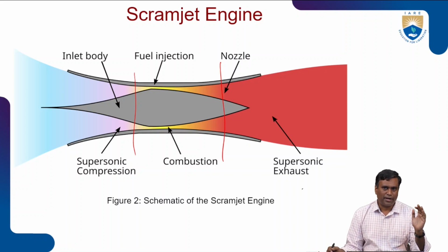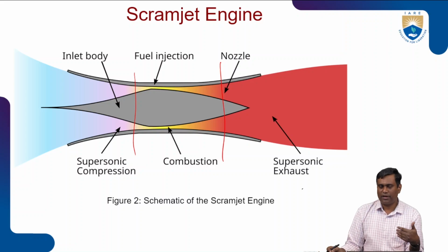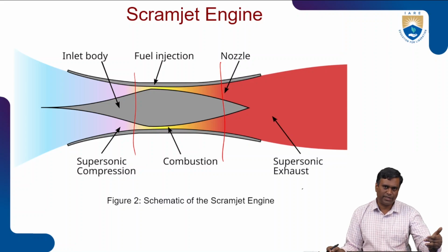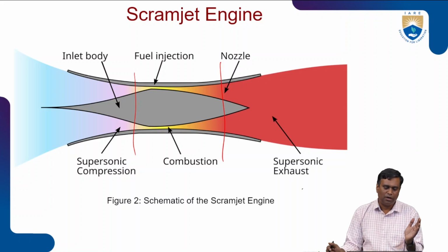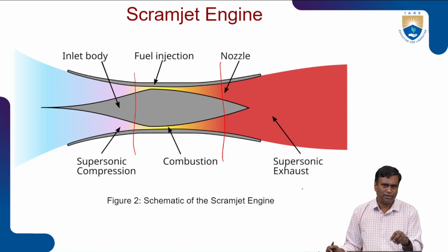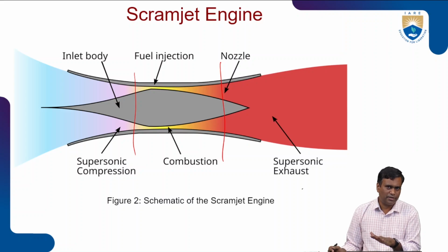In the ramjet case, that particular inlet should handle that and decelerate, right? In both cases, with the help of oblique shock waves and a normal shock wave, the deceleration takes place, by generating different types of shock waves. In the scramjet, we had better avoid the word deceleration, because combustion takes place at supersonic speeds only.